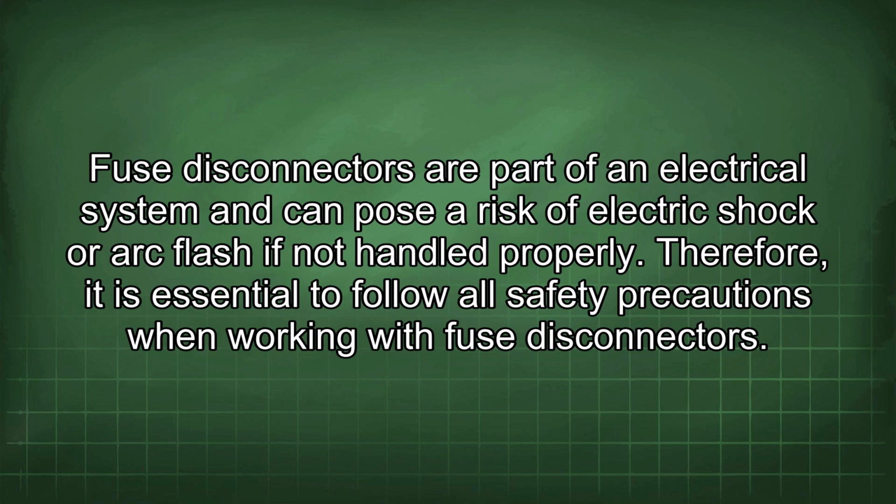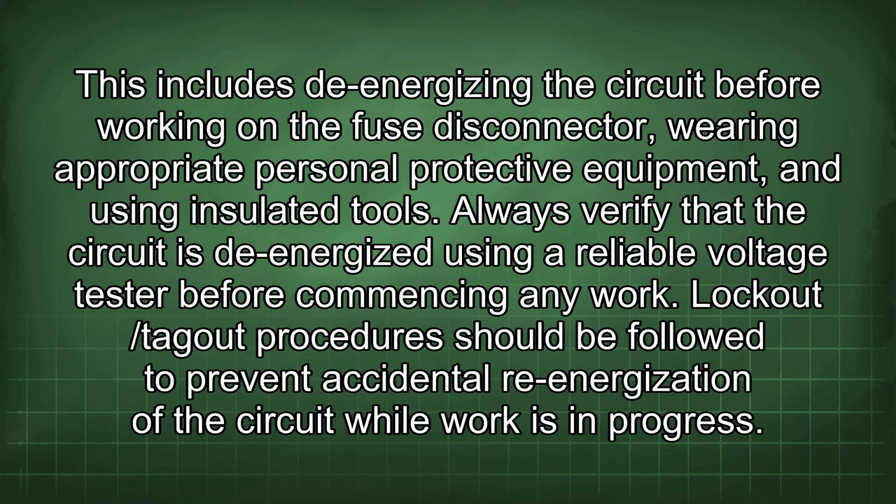Therefore, it is essential to follow all safety precautions when working with fuse disconnectors. This includes de-energizing the circuit before working on the fuse disconnector, wearing appropriate personal protective equipment, and using insulated tools. Always verify that the circuit is de-energized using a reliable voltage tester before commencing any work. Lockout/tagout procedures should be followed to prevent accidental re-energization of the circuit while work is in progress.